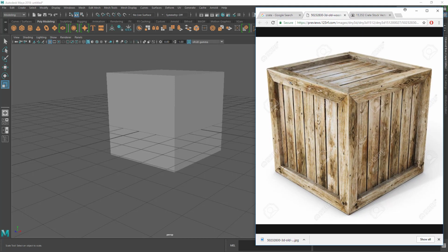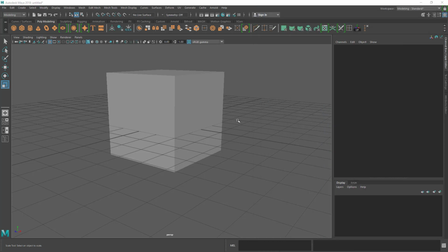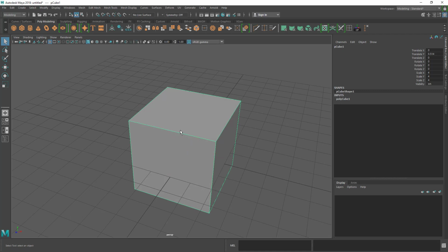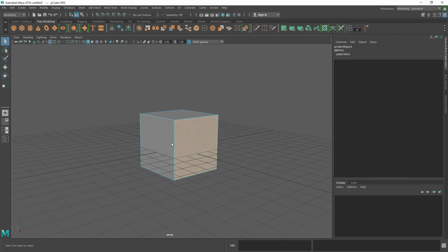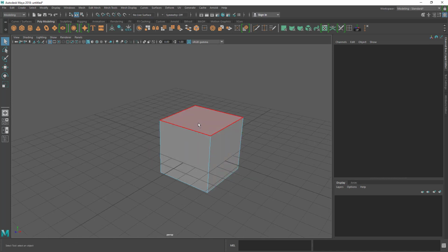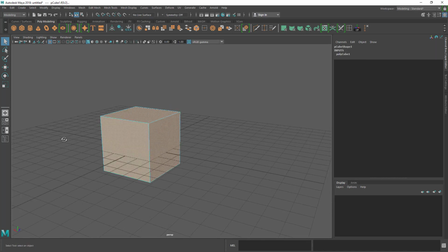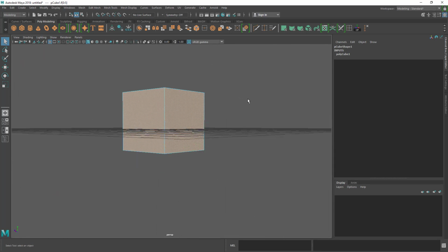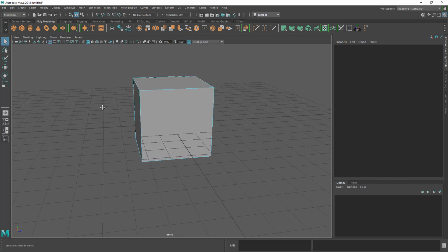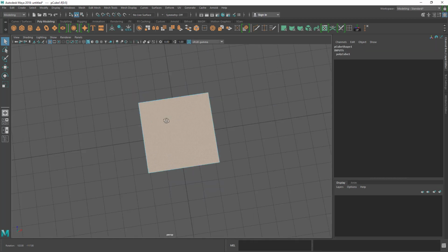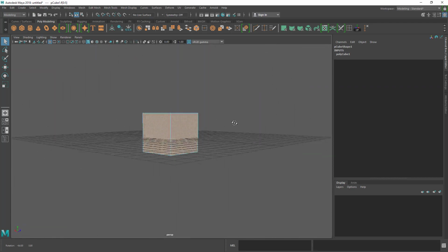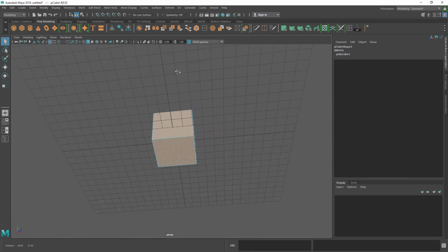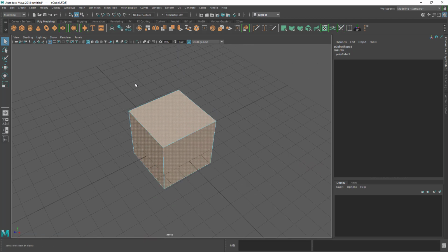There we go. We will basically cut out these grooves, but we don't really cut out in 3D, we extrude. So what you want to do is click on the model, go to faces. Okay, so you want to select all the faces. You can do that by left clicking and holding shift, or seeing that it's just a box this time and nothing too complex, just left click and drag and that will select all the faces. Make sure you rotate around it by holding Alt and left click to make sure you have everything selected.